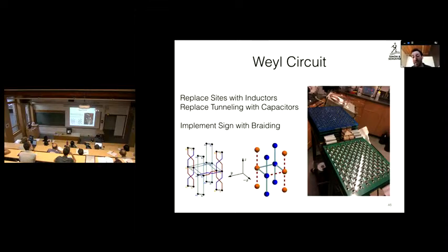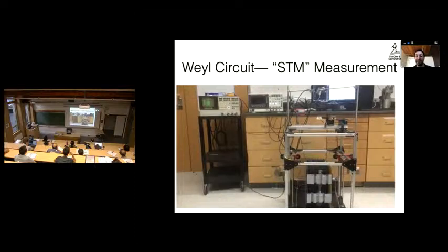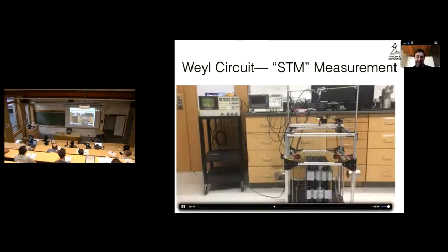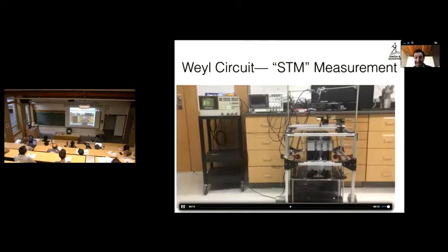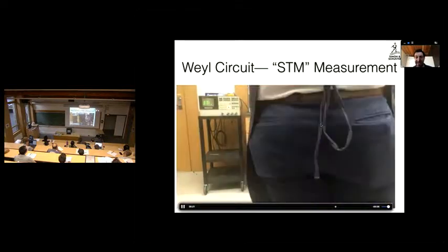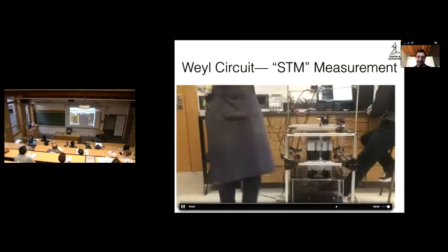But anyway, you solder together these 10 printed circuit boards. And then this is a movie of what the measurement process looks like. Literally what we have here is essentially a scanning tunneling microscope, with these 10 by 10 by 10 lattice. And we've destroyed a 3D printer and replaced the print head with an inductor to measure. And then you collect the data on this network analyzer.